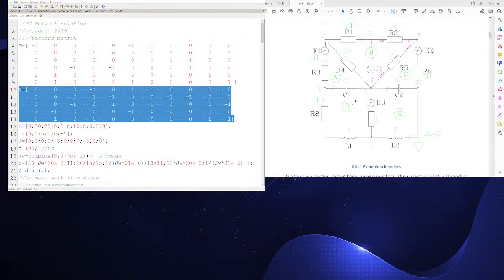For each contour, here they are A, B, C, D, and E, I also need to select a so-called walk-around direction. Some imaginary traveler will go around and collect all voltages to write the second Kirchhoff law, the Kirchhoff voltage law: the sum of all voltage drops on the contour should be 0.